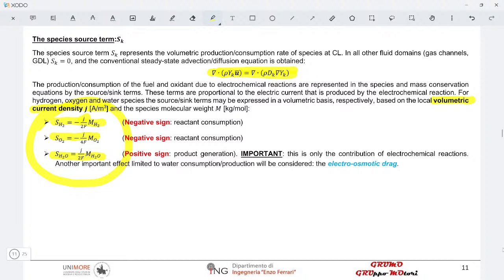And just to conclude this, it will be the summation of this K species that will create the source term of mass that we have seen in the first equation. Okay. So now I hope that it is clearer. Why do we see an apparent destruction or creation of mass? It comes from the electrochemical reaction of each species, which will sum up as a source term for mass. Okay.